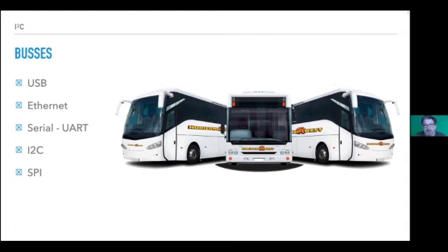What it has in order to figure out who should talk and who to chat with is that everybody has a name. Everybody has what they call an I2C address, but it's kind of just an ID. It's a name. Like if you sit in a classroom and say, Peter, your turn to talk. Then Peter talks and nobody else talks. And the same is for I2C here. You simply just say, who do you want to talk to now? And then that chip talks. The chip knows its own address.